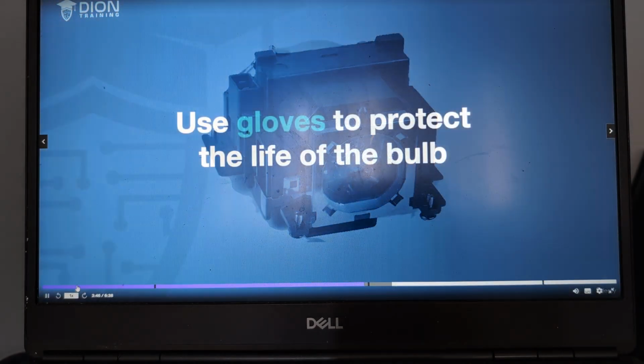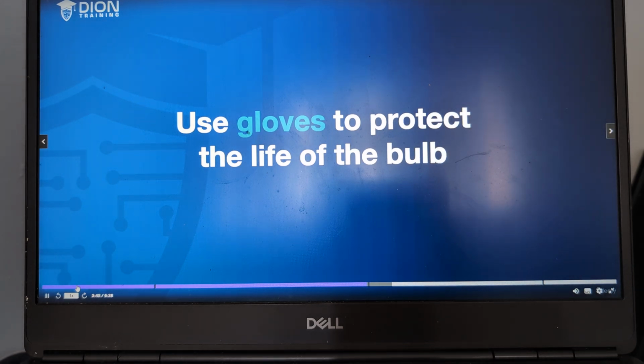When you're replacing one of these bulbs, many of them are actually very sensitive to our hands and the oils in our skin. So you want to make sure you're using a glove, not necessarily to protect yourself, but to protect the life of that bulb, because the oils in your hand can break down that bulb and cause it to have a premature end of life faster than it normally would. And again, these bulbs are expensive, so you want them to last as long as possible.